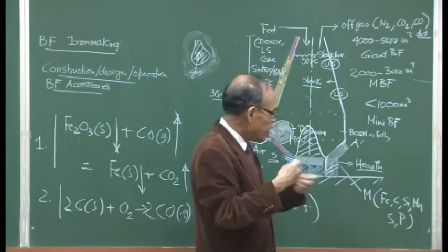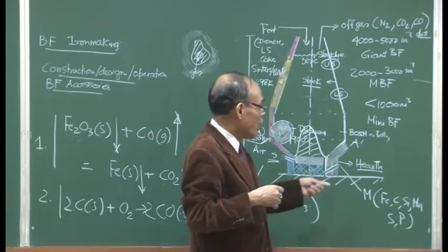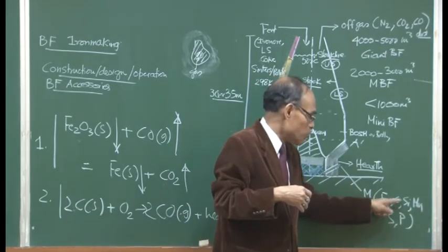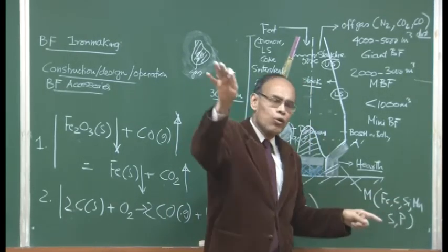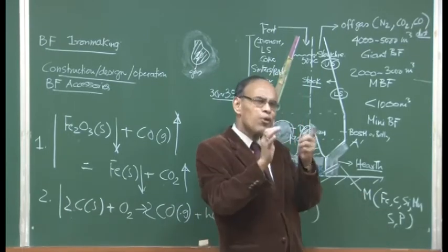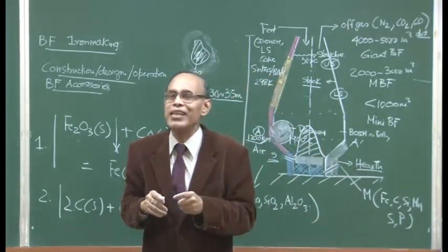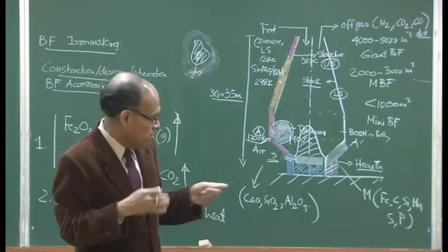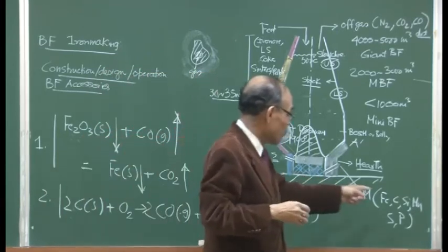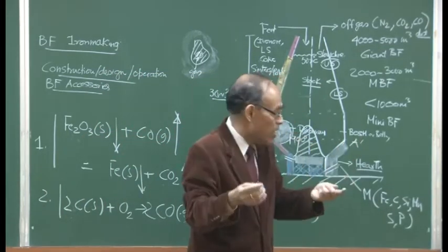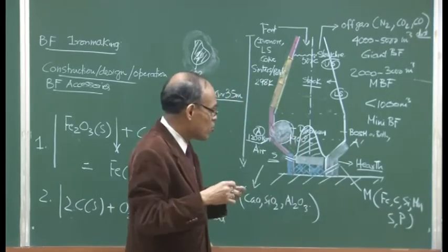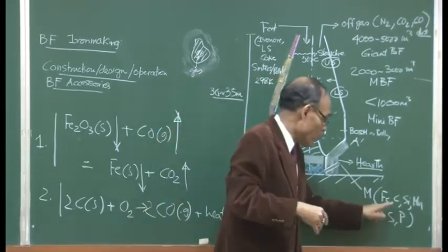It is a brittle material, doesn't have much toughness, so that is not good for us to be employed in engineering applications. On the other hand, if you can control carbon, silicon, manganese, etc., and eliminate a good part of it, then we produce nearly pure iron with less than 0.1% other alloying or impurity elements, and then it becomes steel, and then we get the required strength and so on. So subsequent refining of this is necessary.